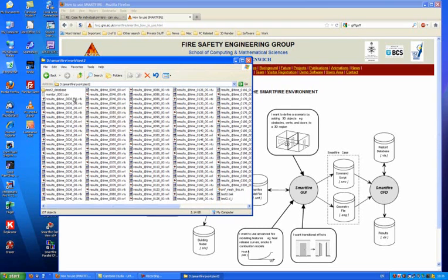The VTK is a legacy format that we will shortly be removing, but the VTU is the most up-to-date format and contains the field data for all of the variables that have been saved. The WRL is a geometry format that contains the surfaces which will actually give the data context.